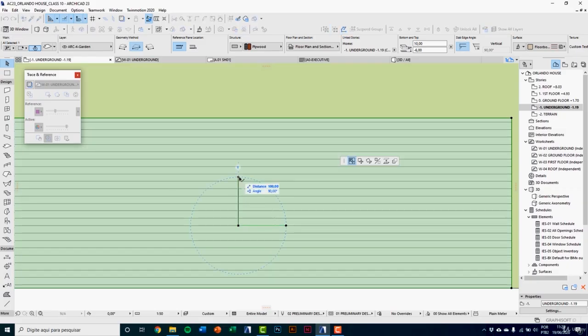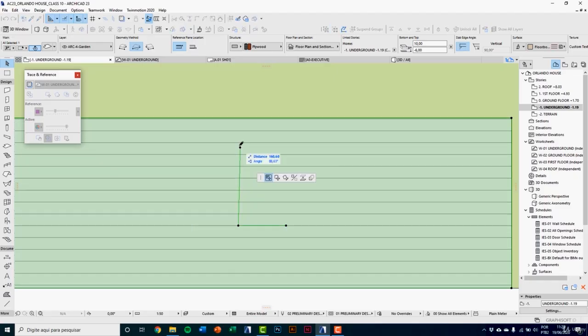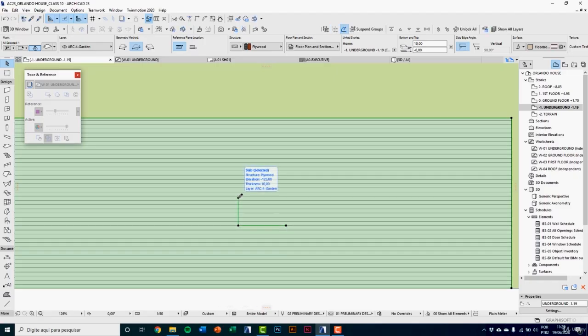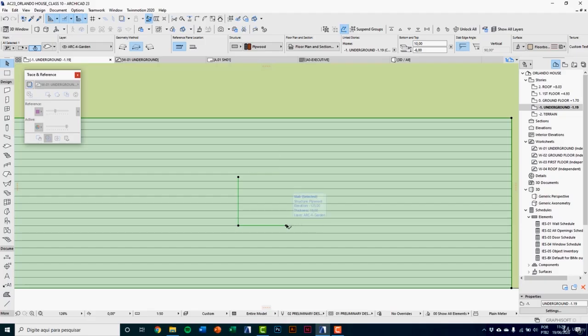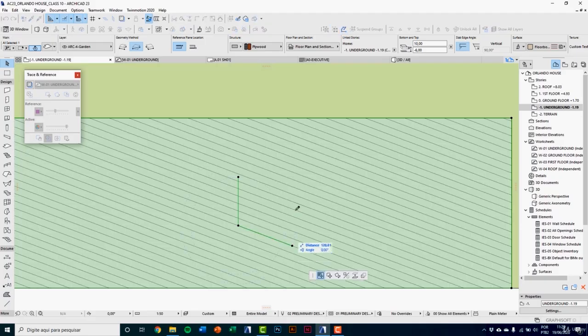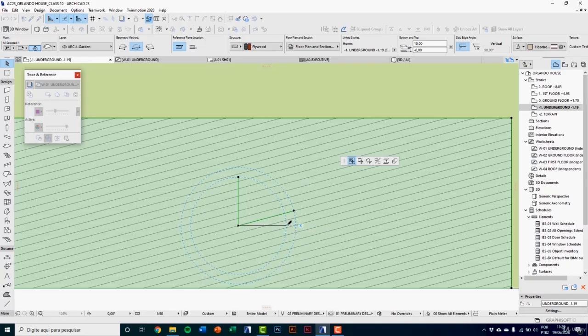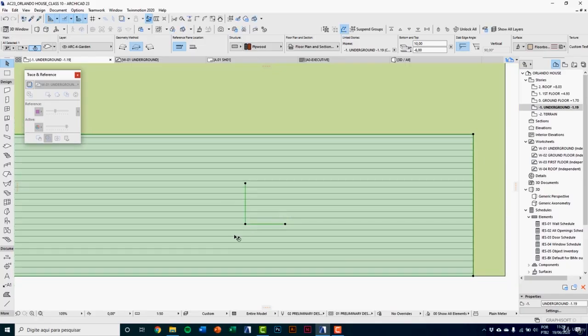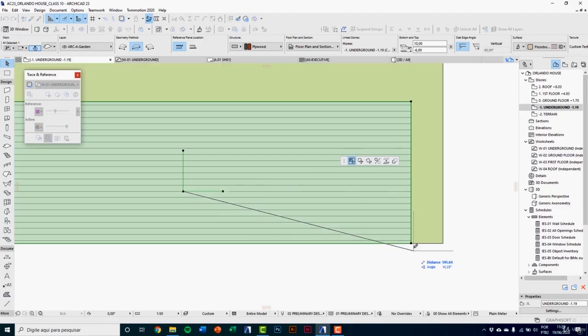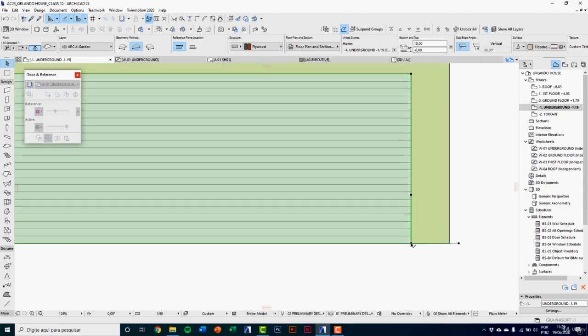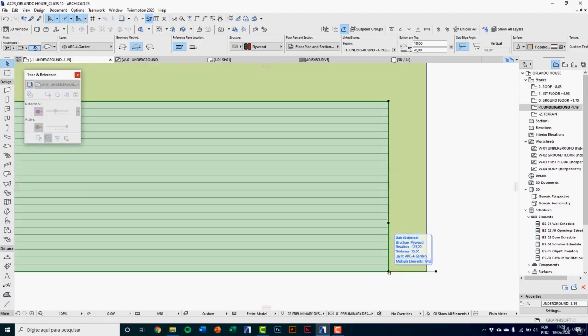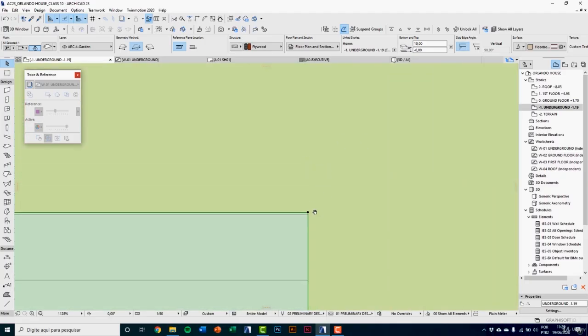The vertical line determines the fill scale. To keep the real scale from plank floor fill, we need to set 1 meter. The other line defines the fill angle. So here I'll place it at the corner, and now on 2D representation the fill is almost correct. You see a little difference. In the end, the line is not exactly matching the edge.